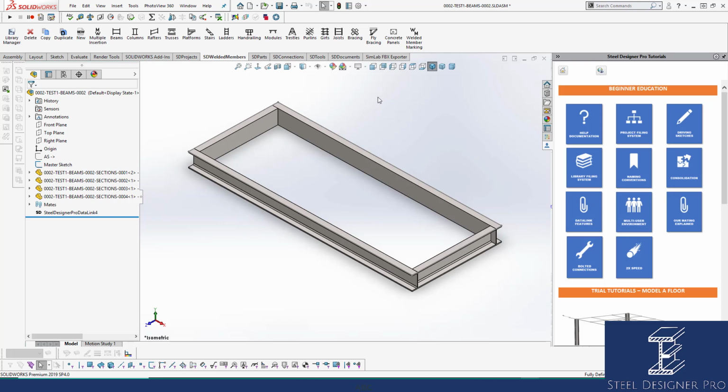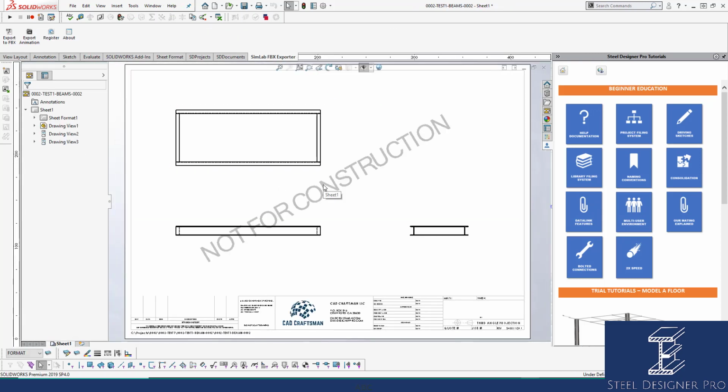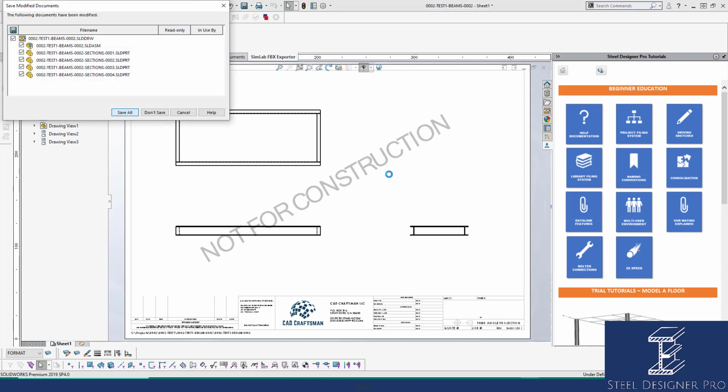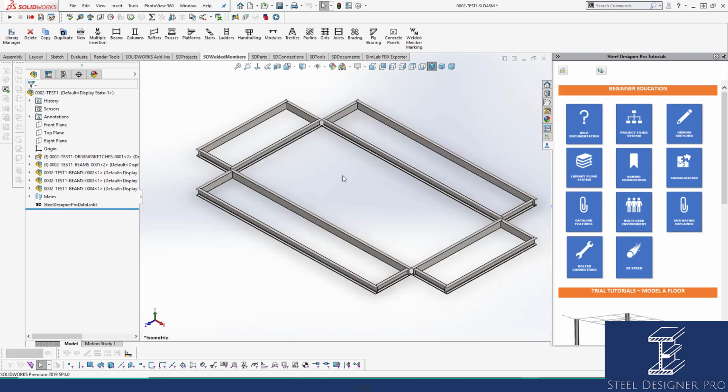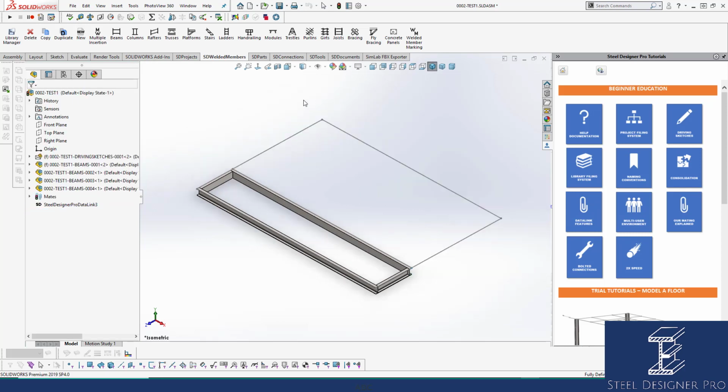Before I copy my welded members, I should have made sure that my welded member drawing was ready for me to duplicate. Otherwise, I've got to go back through my welded member drawings and update them. So you want to make sure that they are actually spot on before we even duplicate. If that's a problem and you've done that, but you haven't put much work into it, you can actually go back and delete your welded members and do it again. So all I'm doing is just selecting sections that belong to each welded member, and now those welded members are gone.